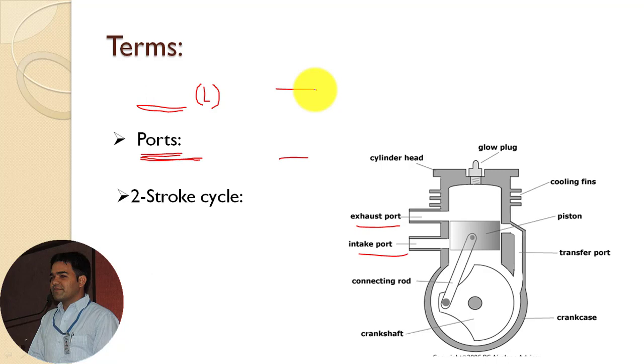In the construction of the two-stroke engine, three ports are utilized: the intake port, the exhaust port and one other port which is known as the transfer port. This transfer port is a simple channel which connects the combustion chamber to the crankcase in this manner. Now the actuation of all three ports, intake port, exhaust port and transfer port, is controlled with the help of the piston's movement inside the cylinder. The remaining parts and construction of the two-stroke engine are quite similar to the four-stroke engine.